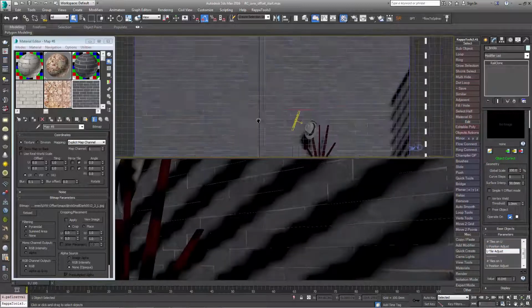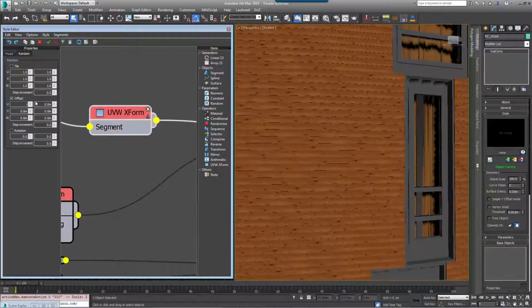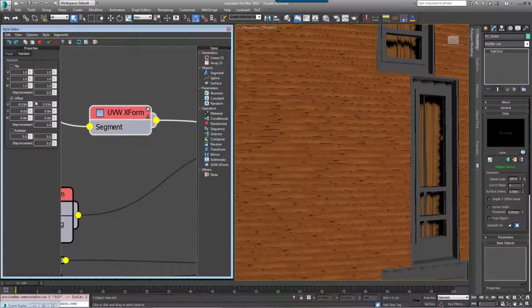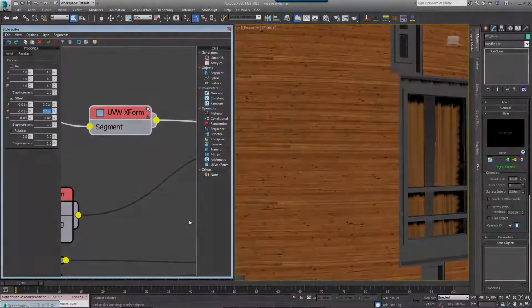Of course, for some uses, you don't need to use step values at all, and you can randomize within the full range of the UV offset and rotation values for each segment to create nearly limitless variation. This is much simpler, often requiring only a single node, and to see how it's done, check out the Railclone 2.4 Features Tour video for an example.